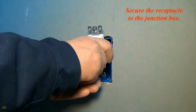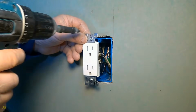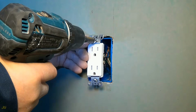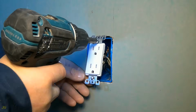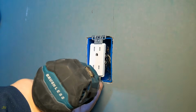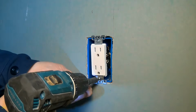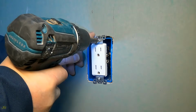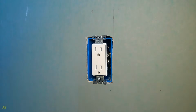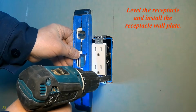Secure the receptacle to the junction box. Level the receptacle and install the receptacle wall plate.